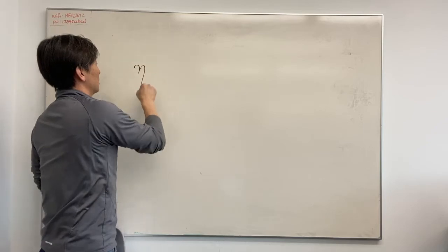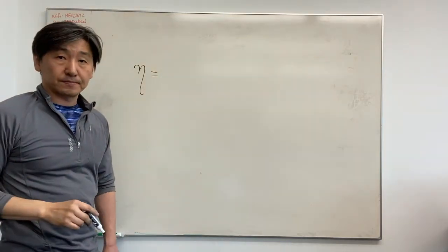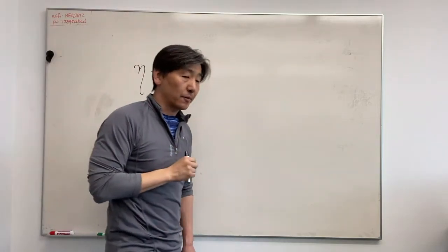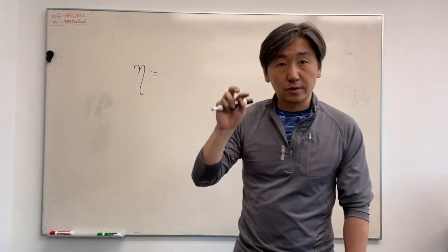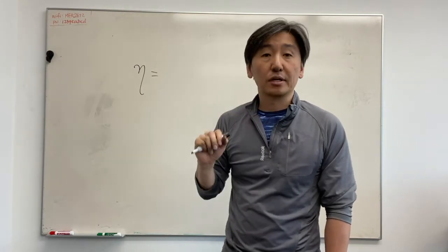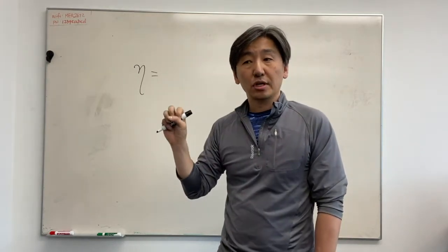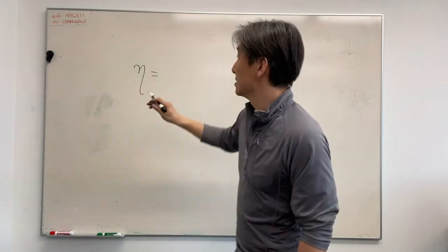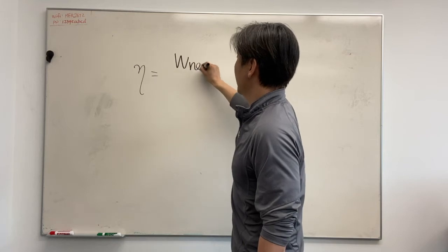Now, your thermal efficiency, in general for a heat engine, can be calculated by having a desired output, in this case the net work, compared to the required input, in this case Q in. So let me write it down again.